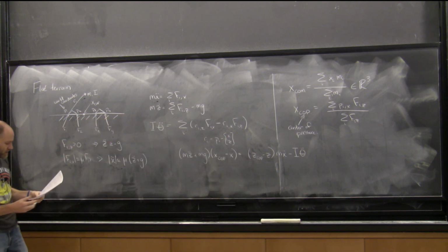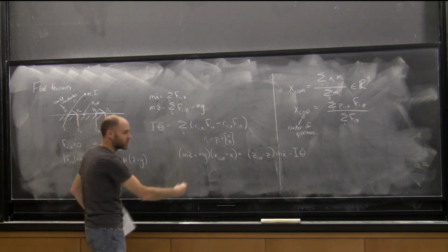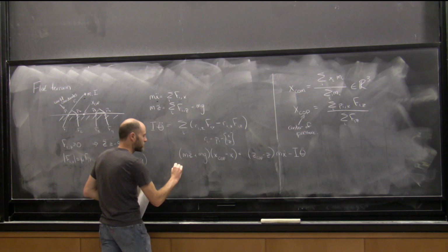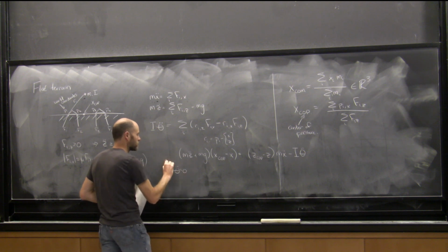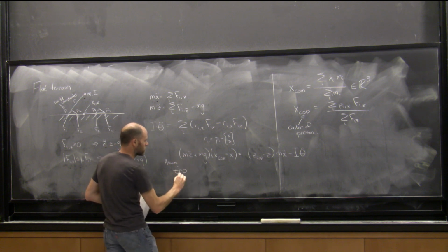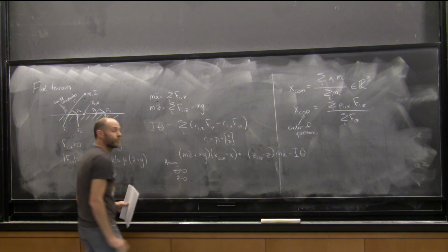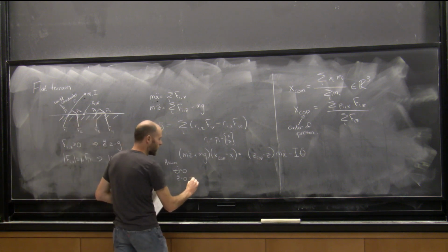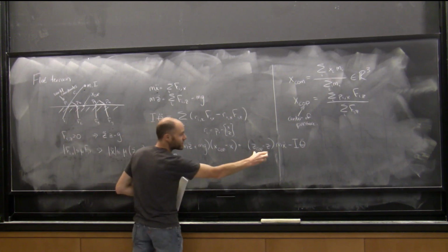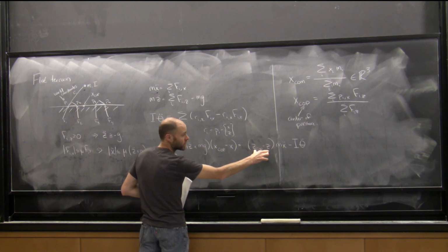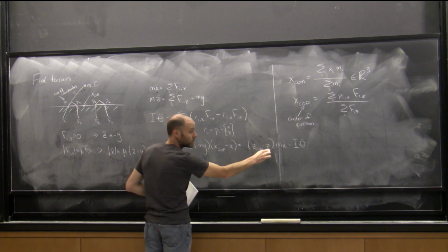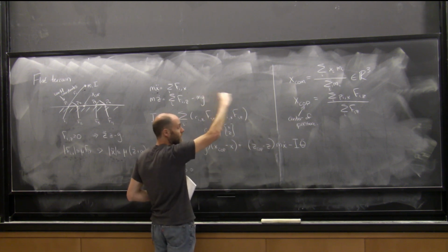And the interesting thing is, if I now take those assumptions that theta double dot equals 0, and z double dot equals 0, z double dot equals 0 also implies that the location of the center of pressure, we know to be on the ground, and that means that the height of the robot stays constant.